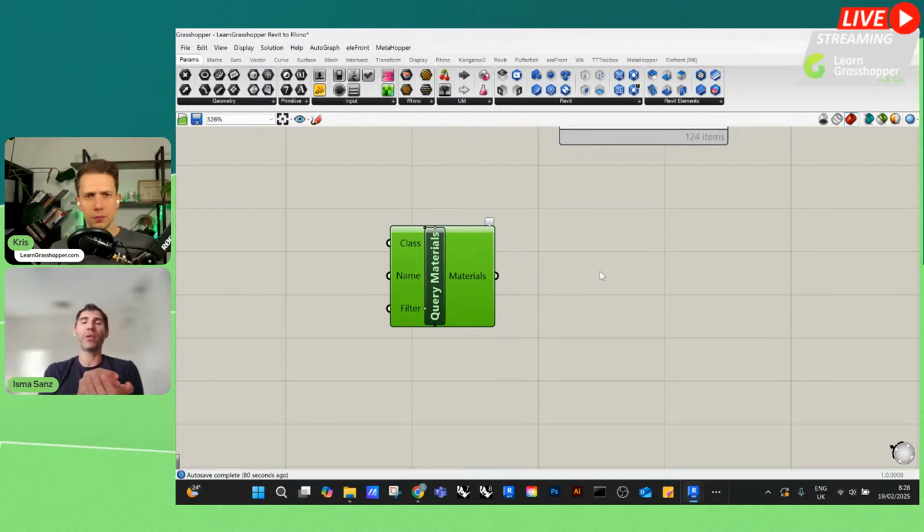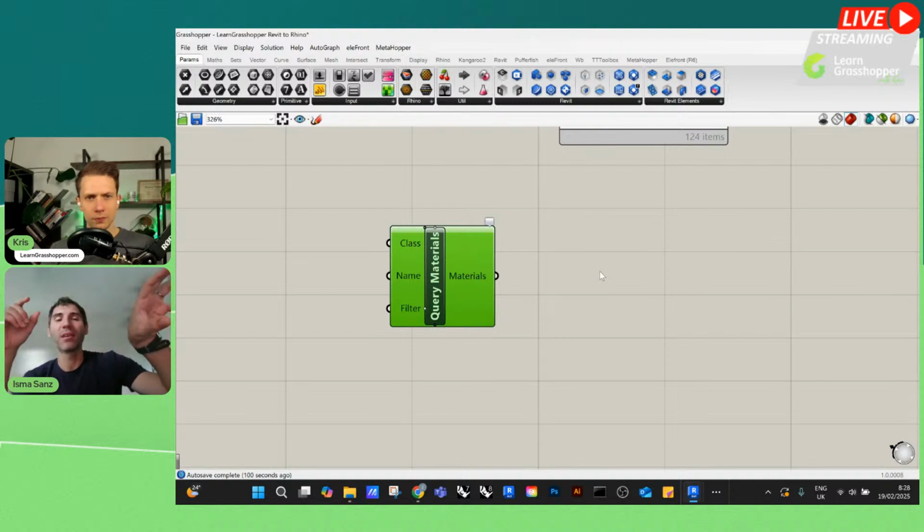So if, for example, you create a geometry, a direct shape, a piece of geometry, and you put it into Revit with Rhino.Inside, it creates a connection between the Revit file, Rhino, and the Grasshopper script. But if you close and reopen the file, it's not baked inside the document.